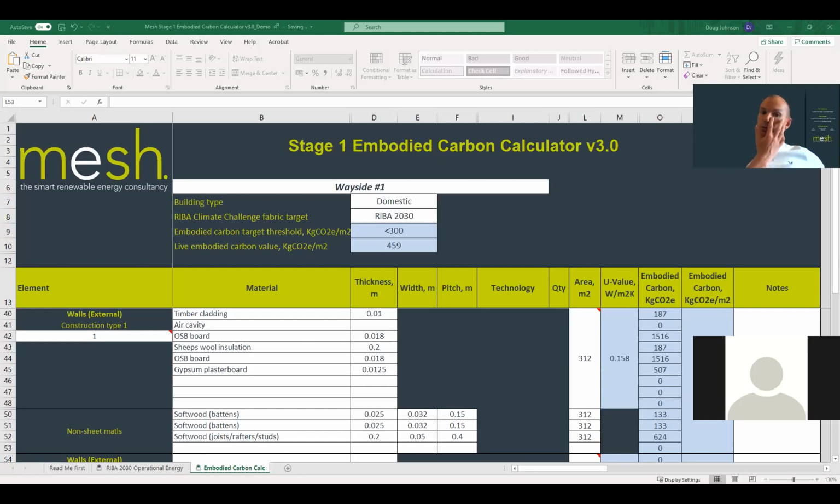Okay, this is a really interesting one as well. So Jana's also asked about essentially sequestered carbon. Now, this is a big thing that's coming up because as part of BREEAM calculations, sequestered carbon is included in the calculations for carbon offset. And what we mean by sequestered carbon is things like trees and natural-based materials have absorbed CO2 through the lifetime of their growth. Funnily enough, an aerated concrete block doesn't sequester anything, a clay tile doesn't sequester anything, but trees and plant material does.